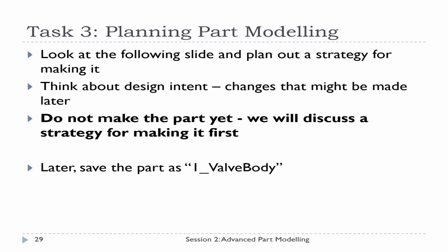When you are making your part, you should be careful about how you create your features, and make your part so that if you'd like to modify it in the future, it can easily be modified. So any change that might be made later should be captured in design intent.